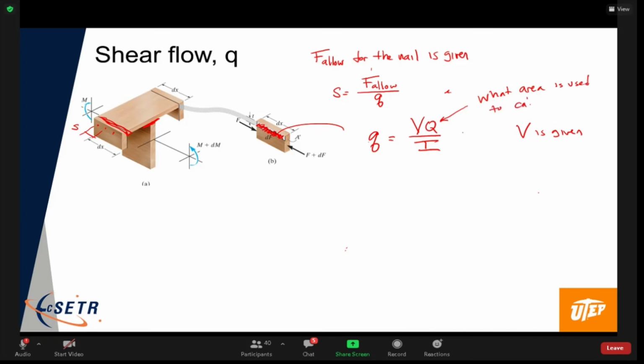It wouldn't be like the plane where the shear will act for that certain part. Okay, but now look, if we zoom in, I'm going to draw it really. So there it is. There's the nail joint. So what plane do you want to use? You want only the top section, not the whole plane. Okay, so this plane doesn't really make sense, because that's not where the nail line is. You want to use this section, this plane? Is that what you're saying? Yes, sir.